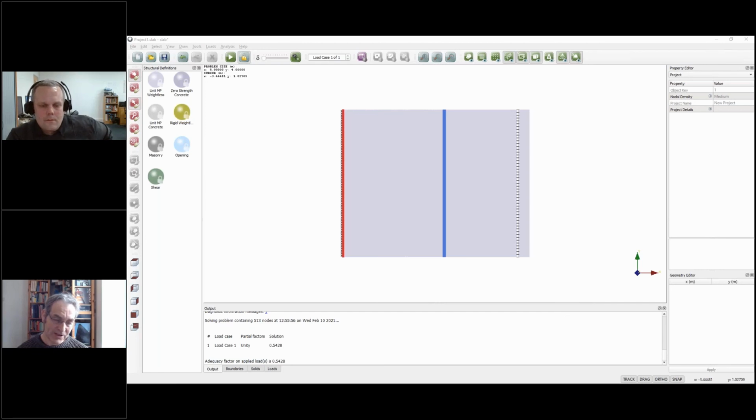whereas the clauses that are used for normal serviceability considerations typically assume 28-day strength and stiffness, and a concern about cracking of brittle finishes if they're actually constructed along with a building. Whereas clearly that isn't going to be the case here. So it does flexural failure very well. However, it's not going to deal with every possible scenario, and punching shear is one of those.